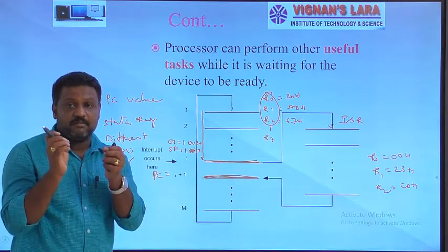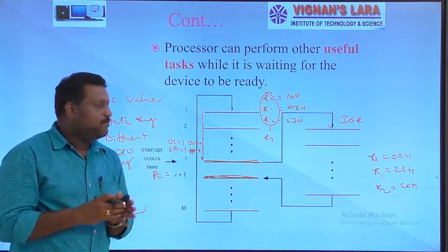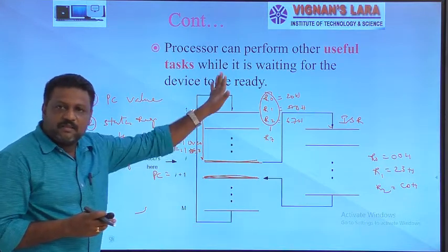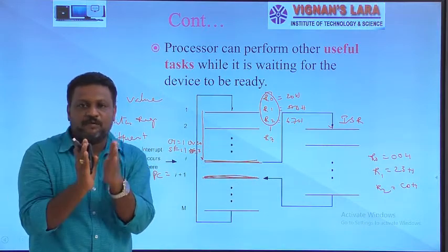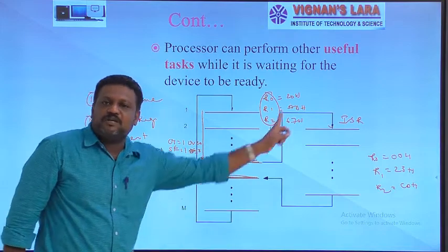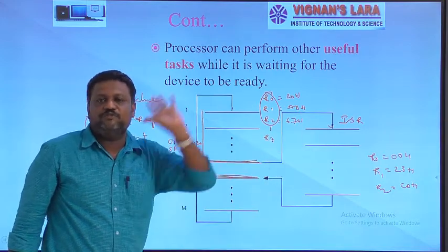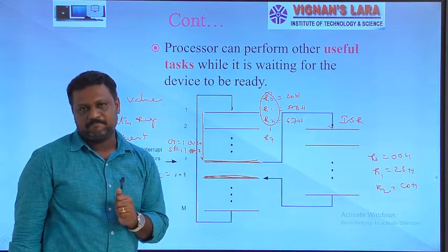Once again, I clearly mention, guys, I am not copying all the CPU register values on the stack before shifting execution from the current executing program to the interrupt service routine. I can only copy the registers which are common for both the executing program and the ISR. Only those few register values I copy onto the stack.